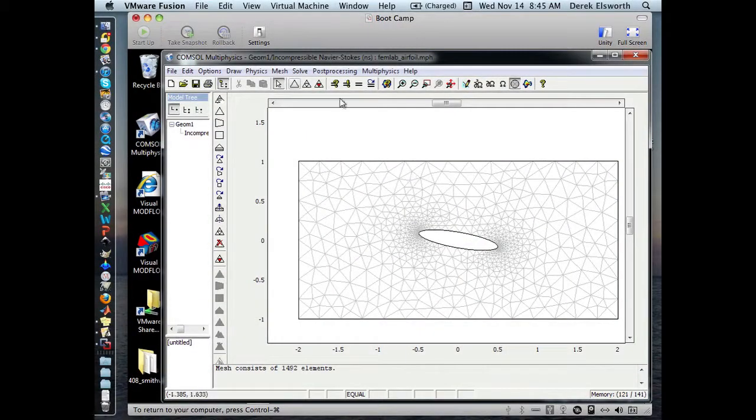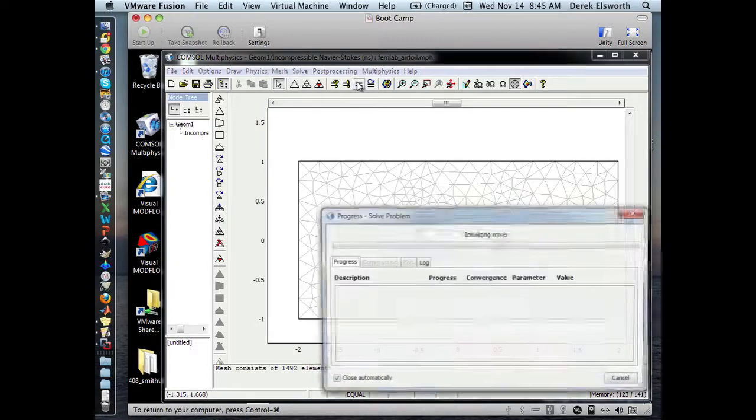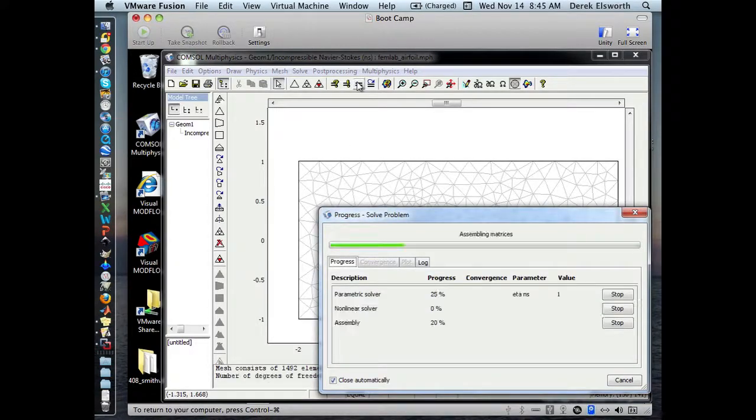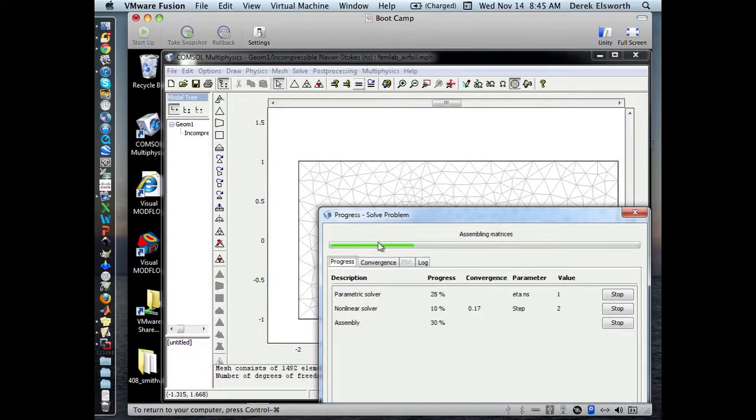If you run it, it runs relatively quickly. It sets up 3 equations for every single point within this grid, and then it solves simultaneously to get a solution that fits the boundary conditions. Nothing other than that. I'm going to run it for a viscosity equal to 1, a viscosity equal to 0.1, a viscosity equal to 0.01, and also 0.001. If I do it for the next one, it doesn't solve it because it's a very high Reynolds number. It doesn't solve easily.